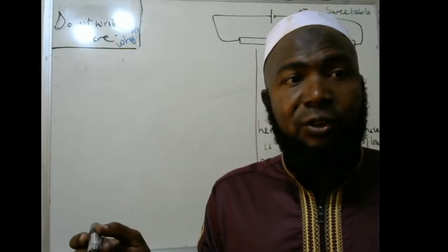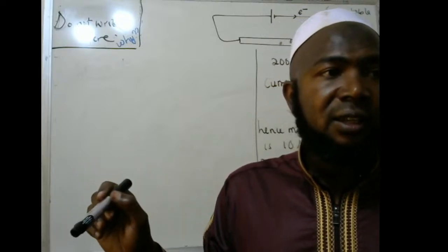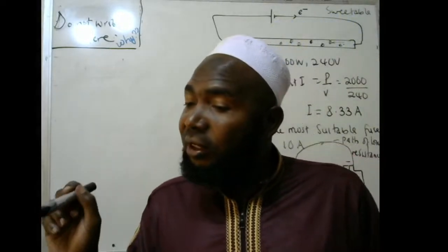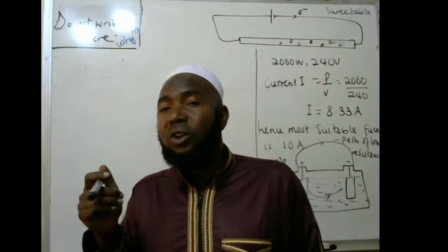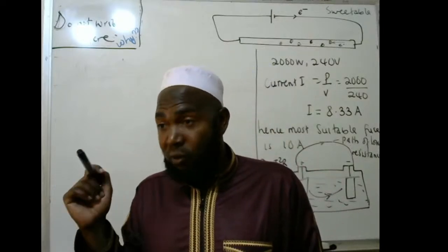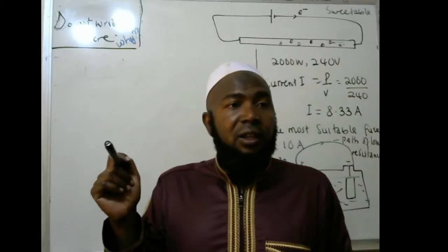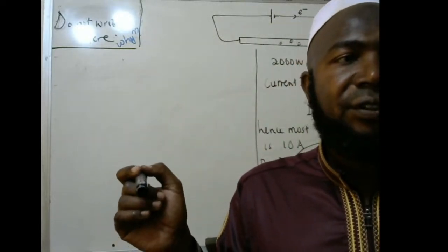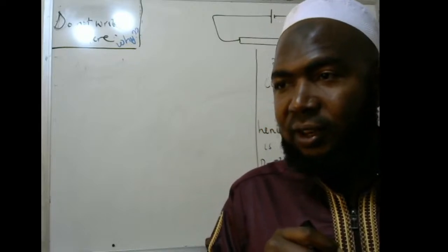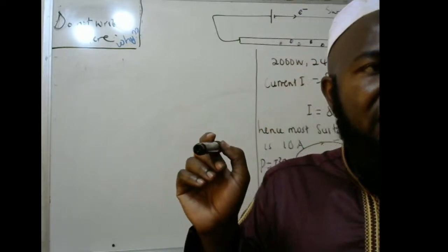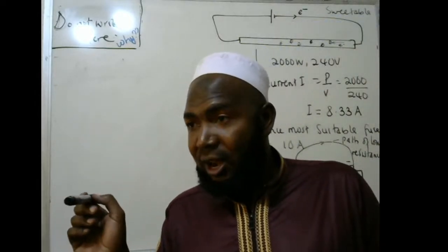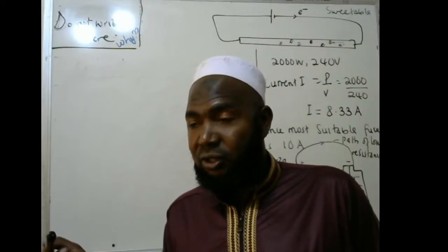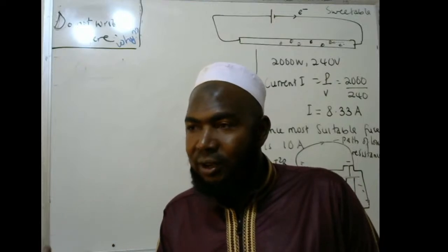Ampere. So what the fuse does is to disconnect the circuit. The difference with the switch is that this one only disconnects when there is excessive current flow. It disconnects the circuit and protects the appliance against the risk of fires caused by heat. So it only happens when there is excessive current flow. And what it does, it just blows, because it is of low melting point. So if it exceeds the value set, it just blows.